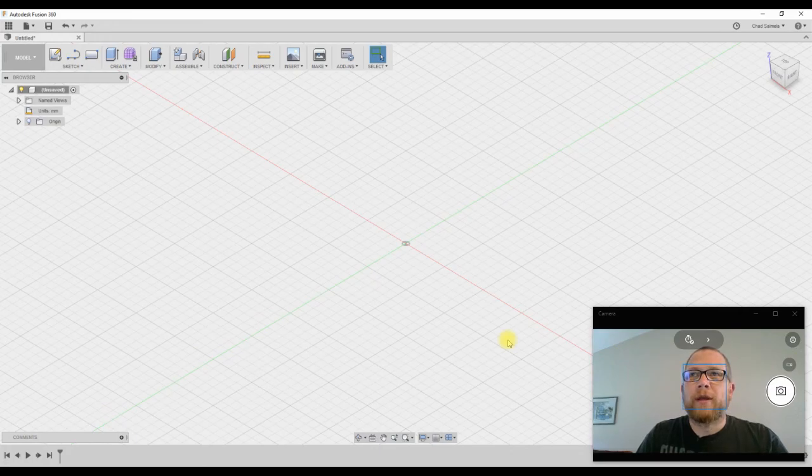Later on, you can use that to drive your models by going back to your parameters and changing your length. Instead of dimensioning something to 12, you dimension it to length, and you use the parameter instead of the physical dimension. Then all you have to do is go back to your parameters window. You can change your parameters whenever you want, and your model will adjust automatically if it's modeled correctly. And that's kind of what I want to show, is how to use parameters.